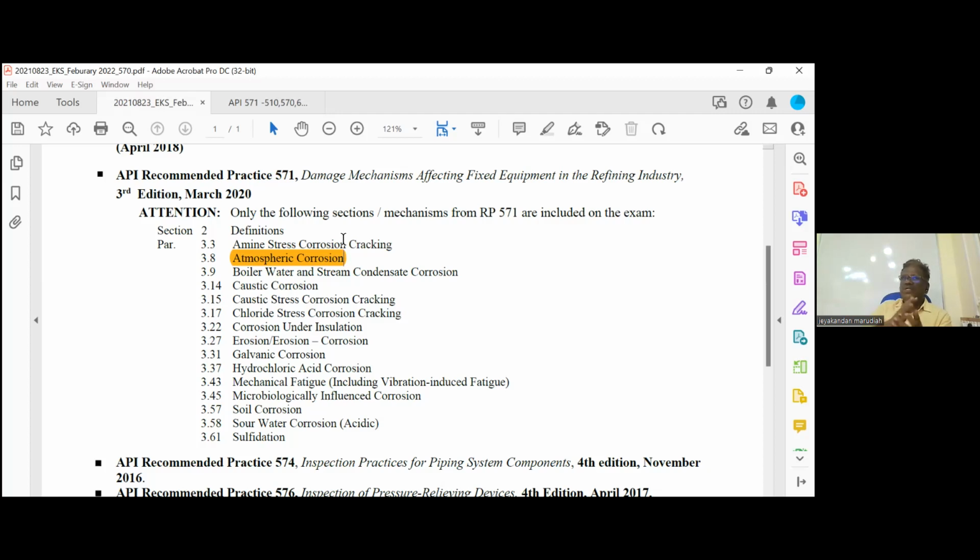Now, I told you temperature and corrosion rate are related. Up to 250, if the piping inside temperature is increasing up to 250 degree Fahrenheit, corrosion rate also increases. But when the temperature exceeds 250, moisture will be dried immediately. So corrosion rate will not increase. That is the cutoff. What is the maximum temperature atmospheric corrosion can happen? Answer is 250 degree Fahrenheit.